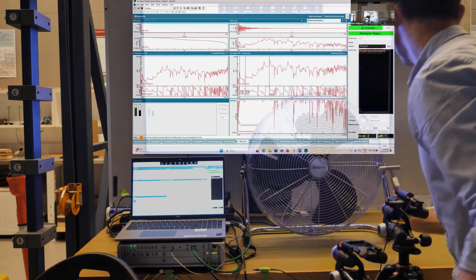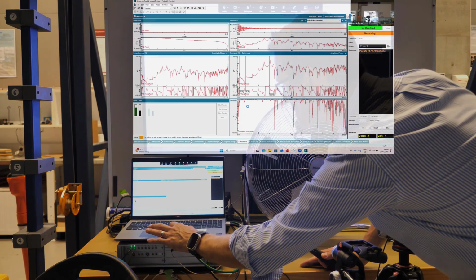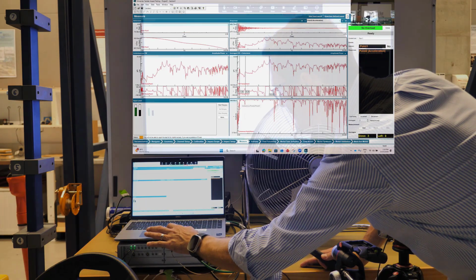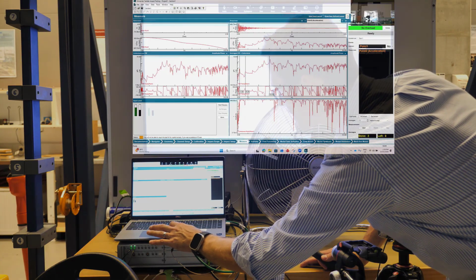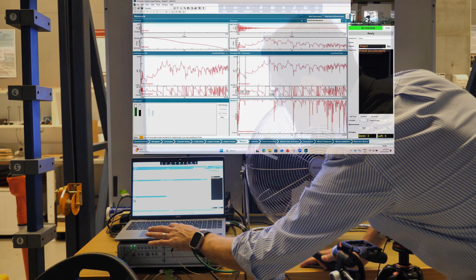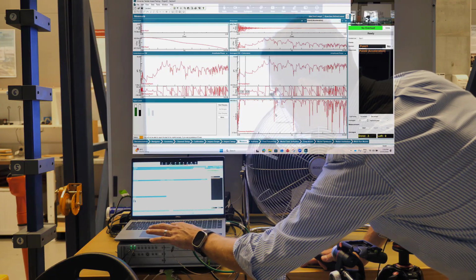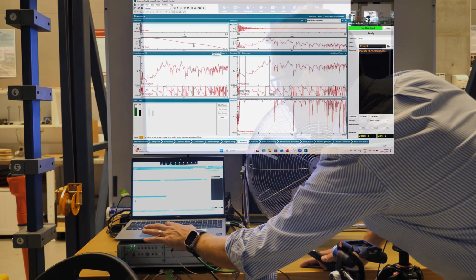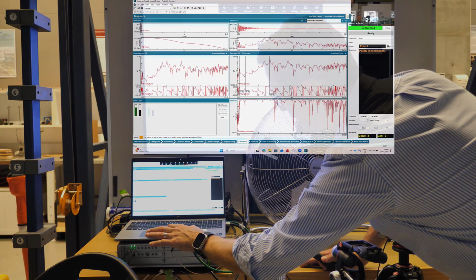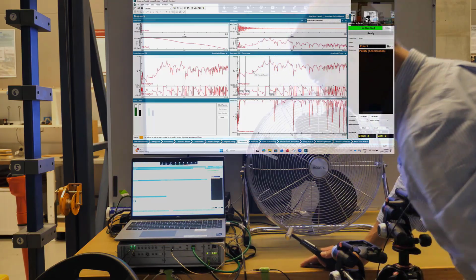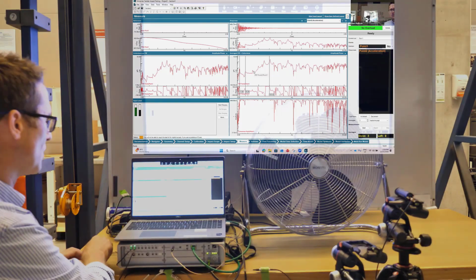And there you can see I've got quite nice coherence. So I've got good signal to noise ratio on the 2 channels, and I'm getting good signal across a relatively wide frequency range, with the exception of that anti-resonance there. So my coherence is a little bit low at this location, and higher up in the spectrum perhaps I'm not getting as much energy at those frequencies into the structure. It's not a very nice looking FRF like we might be used to seeing from single components like cantilever beams and plexiglass plates and other such structures.